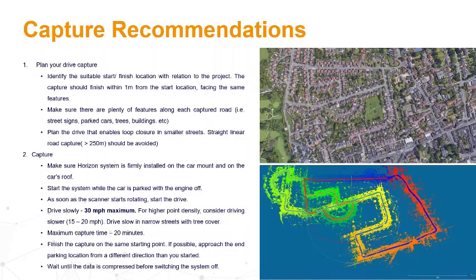So if you do a survey using a car, you should ideally also follow all the rules as if you would do a handheld survey. So not going over maximum capture time of some 20 minutes, and ideally come up to the same point at the end of the loop, within about 1 meter from the start location, the same point facing the same features around you. Also try to avoid when there are too many cars moving around you.